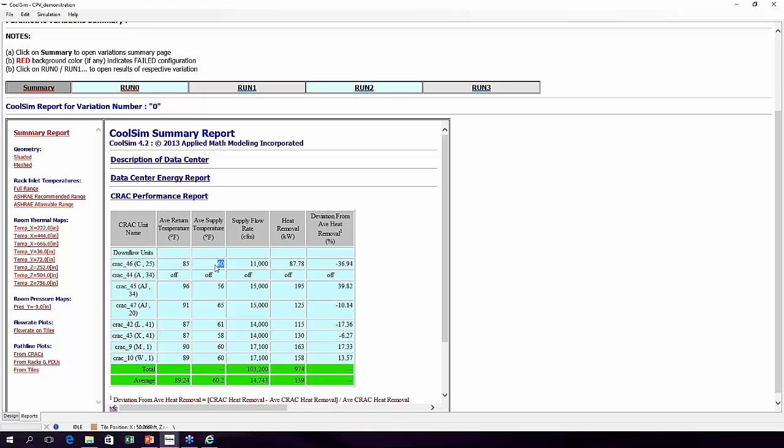So before containment, you'll see this number be generally closer to that number because the cold air is looping back and cooling off the return. And after containment, this number, the return temp, will go up because you've made the air go to the IT units themselves. And when you do that, you get a benefit of energy. In other words, you save energy, and the ratio is about 3.5% per 2 degrees F, or some people like to use a 1-to-1, 1 degree F equals 1% of cooling savings. But you'll also generally be able to reduce this number right here as well.